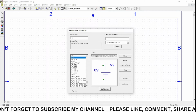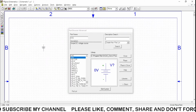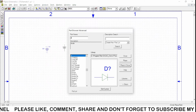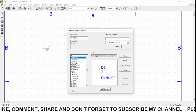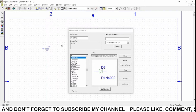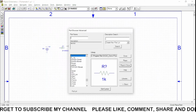So I am taking VDC. I say just place, and it will be attached to my pointer. So I am going to click over here. What we need again is a diode. I'm not going to take only D because it will show some error. I will take a diode which has a name, the model 4002. So I'm going to place it again in here. Then I need a resistance, so I'm pressing just R.